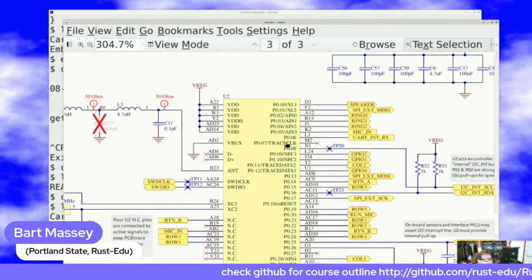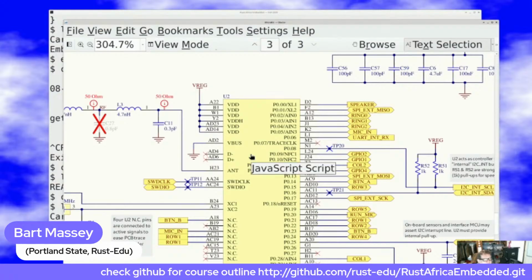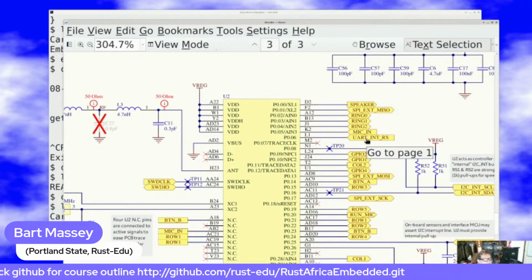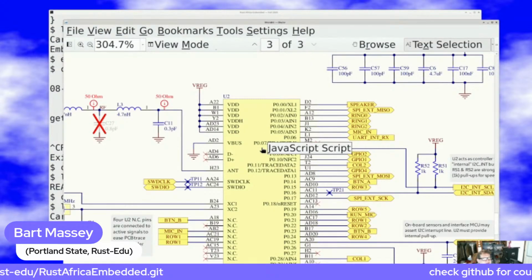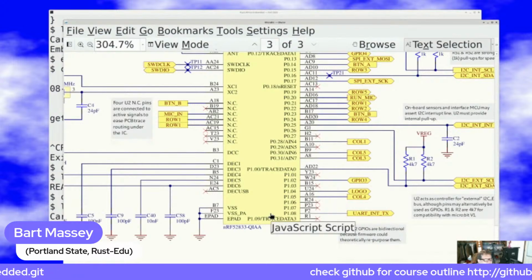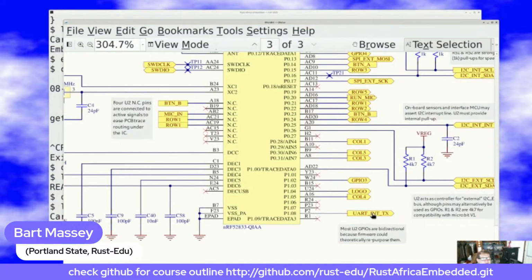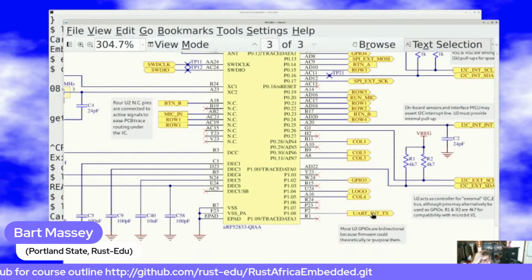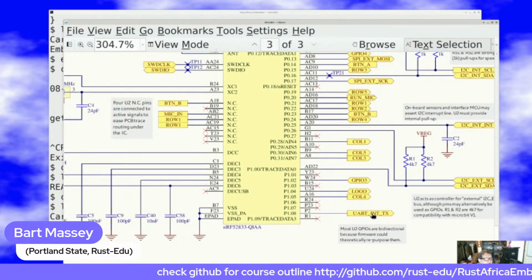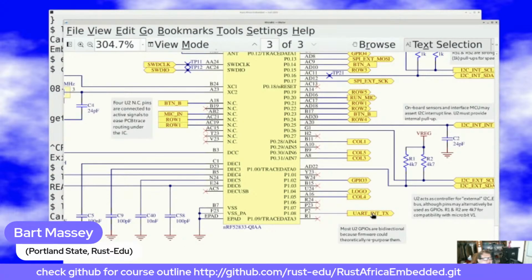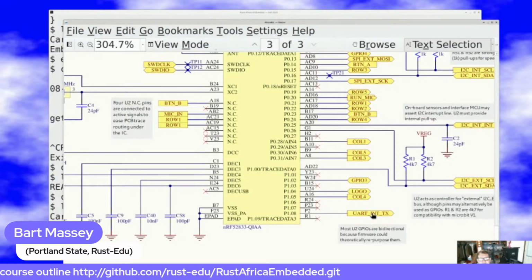And the point is, inside this microcontroller is a bunch of hardware that will reassemble the bits coming in on the serial port into a byte and let the microcontroller know it's there. And on this end, there's a bunch of hardware that will take a byte, break it up into bits, and send it out the serial port. And that's what the UART does. That's a peripheral inside the microcontroller. It's a very fancy peripheral with a lot of modes and options and configuration, most of which we'll ignore. But at its heart, it's a fairly simple peripheral. It is a way to send stuff out of a serial port.